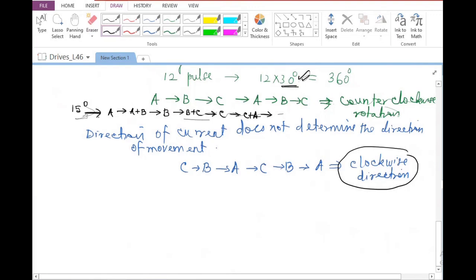So I would be able to adjust the step angle to a very minute value if I am able to fire two of them simultaneously, or if I try to have a 3:1 current ratio, then a 1:1 current ratio, then a 1:3 current ratio, and so on.